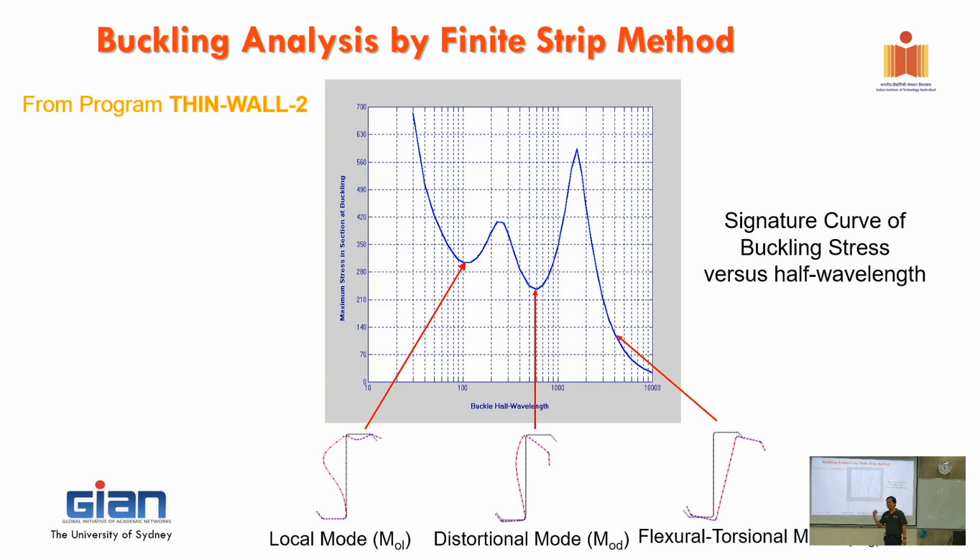This is buckling, okay? So remember, I jump ahead a bit. The direct strain method is the equation where you need two inputs. One input is the yield, and one input is the buckling. All right, and then that will tell you everything. Okay, buckling is showing you the behavior, and the yield is showing you the material side of that. And this equation works, it will cover everything about the imperfection, residual stress, or whatever. So that equation will tell you.